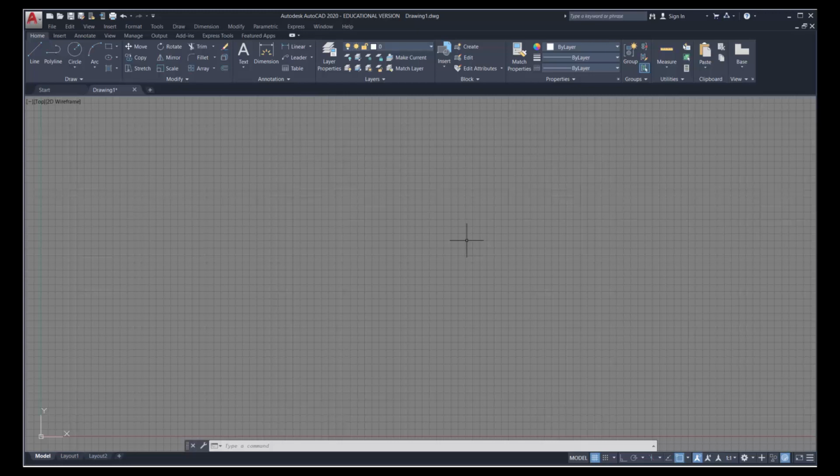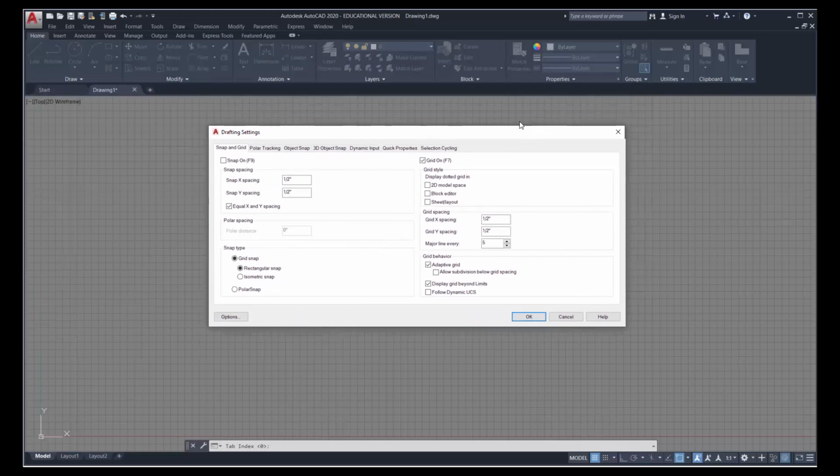In order to see the drawing area, we're going to switch down here into our drawing aids. Again, drawing aids are designed to help us visually see what it is that we're working with. Last day we toggled the drawing grid, and if I click that on or off, I can see that. This time we're going to adjust this grid. So to the right of that, there's an arrow that points down. It's called Snap Mode. I'm going to click on that arrow. This is actually the area that allows us to adjust the snap settings. So when I click on that arrow that points down, you'll notice you got polar snap, grid snap, snap settings. Click on snap settings. And all these terms will become a bit more familiar as we work through the program. We get this menu. The only thing we're going to adjust here is in the lower right hand corner where it says grid behavior.